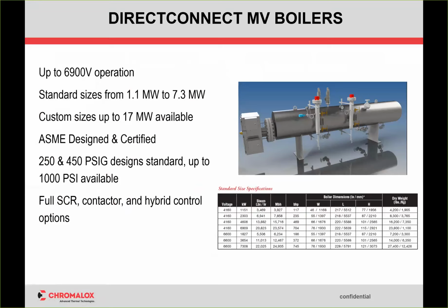The location of them doesn't follow the standard boiler area classifications as traditional gas-fired boilers do, where you have to have exhaust, the boiler operator, incoming gas lines, yada, yada, yada. This doesn't work that way. This is no different than our circulation heaters. This can be mounted in areas, on different floors of buildings, outside, and it doesn't require as much constraining permitting as a gas-fired system would.